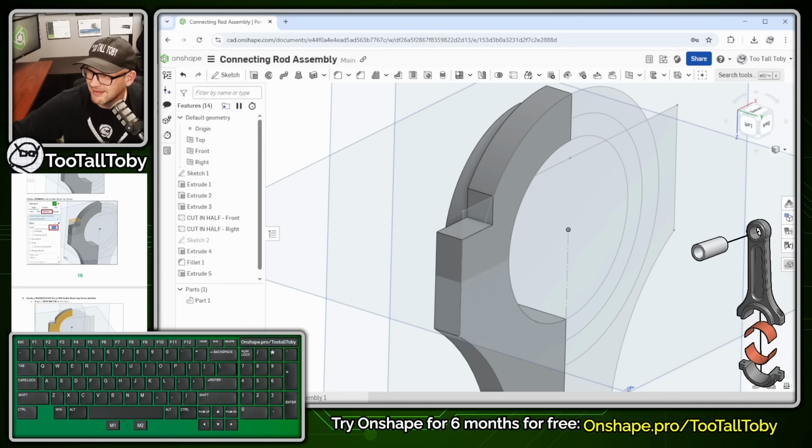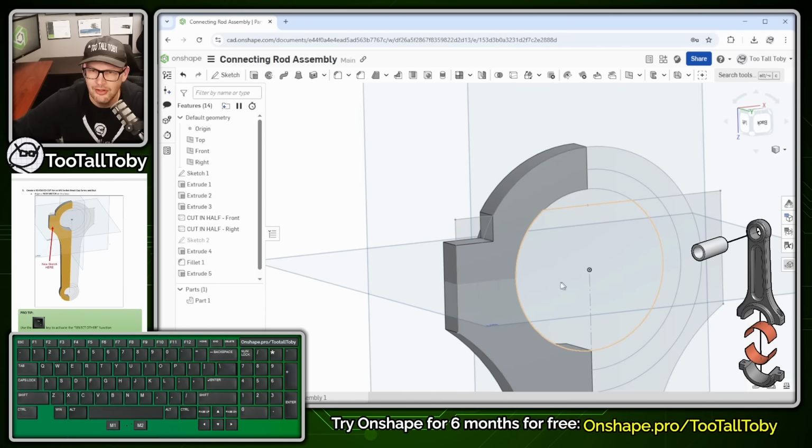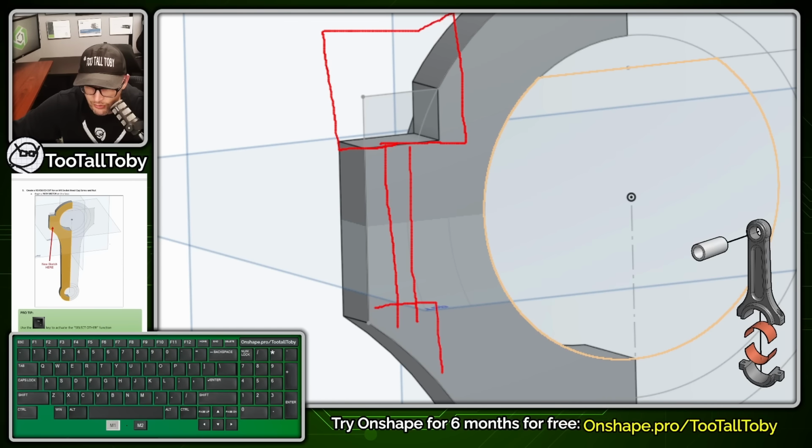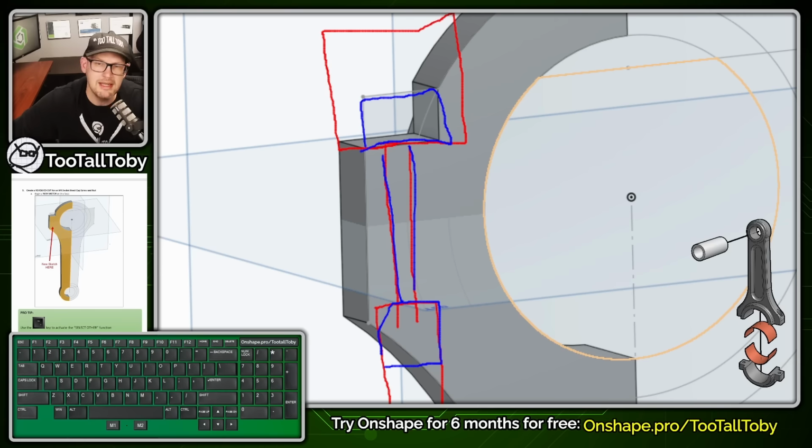So now we're ready to create the sketch for our counter bore. The way we're going to create this sketch is we're going to create some geometry that starts out right here along this edge. And we're going to create some clearance here for the nut of this bolt that's going to be sticking through here. Then we'll create the geometry for the through hole. And then down at the bottom here, we'll create a counter bore to account for the head of that bolt. And we'll make that a socket head cap screw. So the socket head cap screw will sit in here like so, and then the shaft of the bolt will come up through here, and then there will be a nut sitting up top here. So we're going to need to account for that nut. We're going to need to add a little bit of clearance up top, and that's why we're going to create this sketch, what's shown in red here.